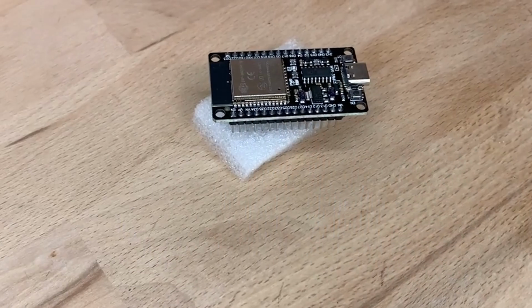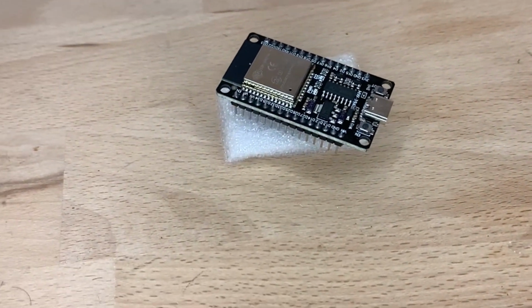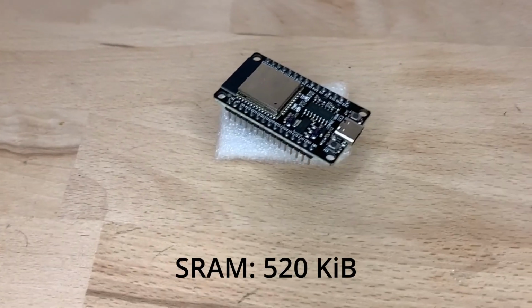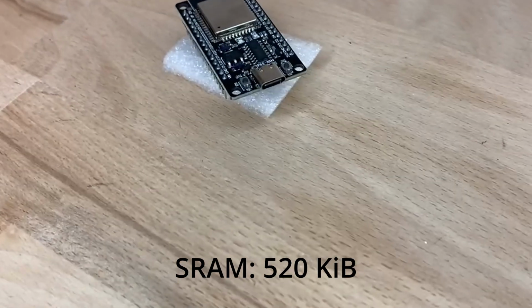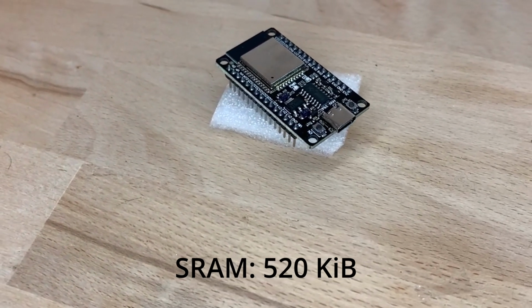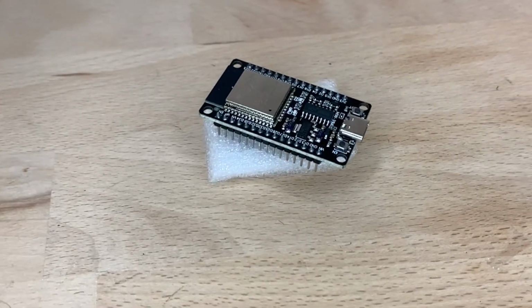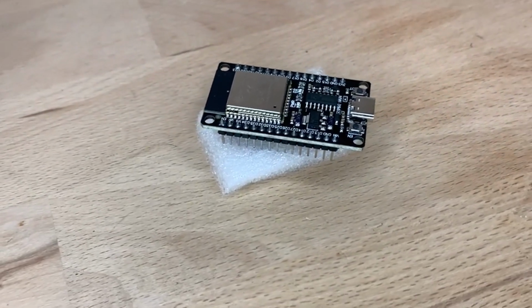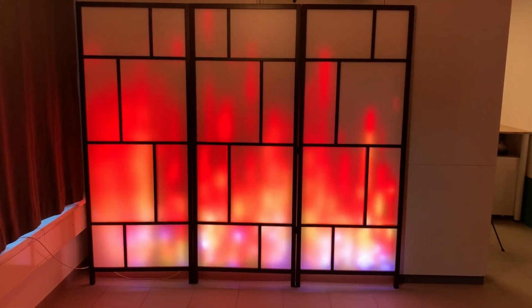This is one of the reasons I chose an ESP32 as a microcontroller for this project. With 520 kilobytes of SRAM, it has plenty of space to buffer these images. It also has Wi-Fi capabilities and ESPHome, which allows this device to be connected to smart home systems. After hooking up the microcontroller with the LED strip, I was confronted with the first issue of this project. It was everything but smooth.